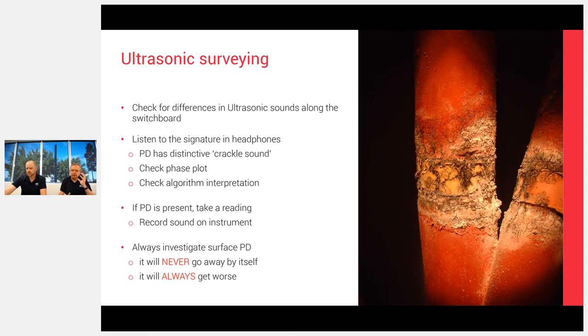But in reality, when you're doing the testing, concentrate on the listening. Don't concentrate on the screen. When you hear something, then use the screen to give you that additional interpretation. So fully focus on placing your sensor nice and gently around all the air gaps and listening for something that is different.